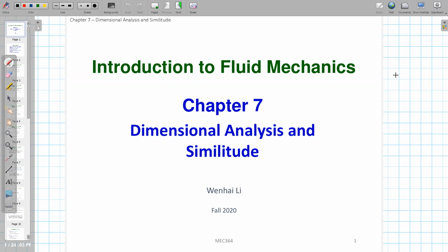And in the meanwhile, we also proved that if you follow along the streamline, the Bernoulli equation can also be derived from the energy equation, okay. And we also realized that for the Bernoulli equation, anytime you want to use it, you must make sure that those 4 restrictions are there, okay. It's inviscid, incompressible, steady, and follow the streamline. This is the first kind of situation where you can use the Bernoulli equation.